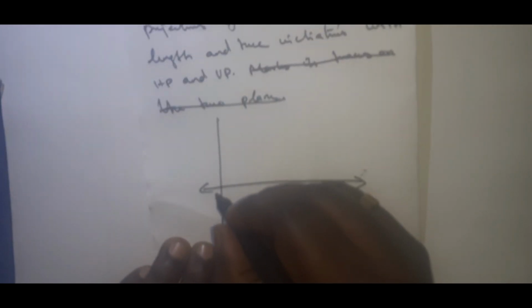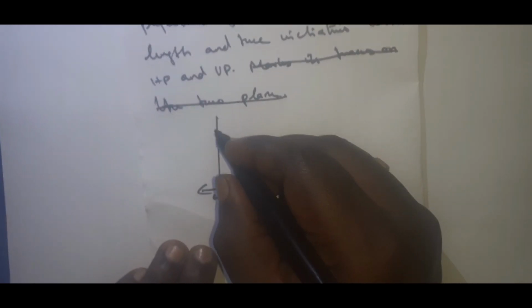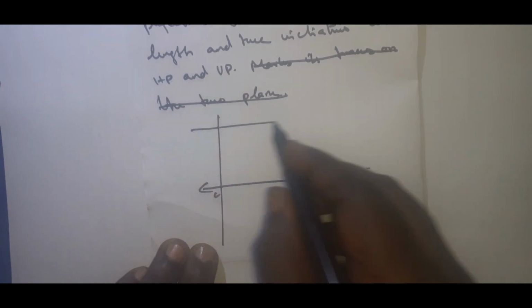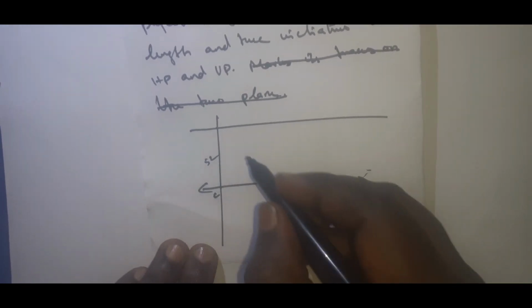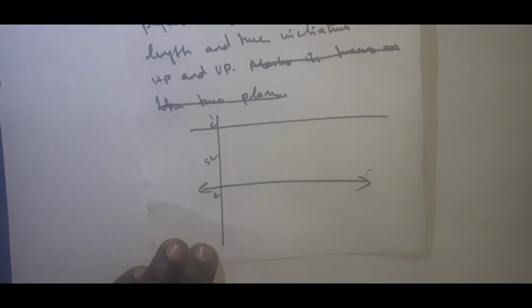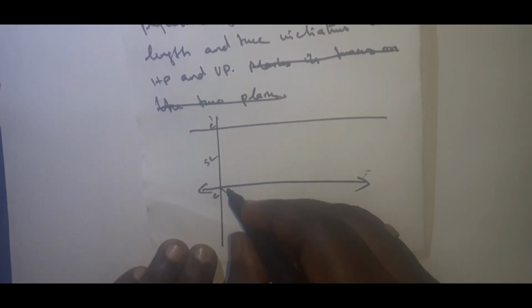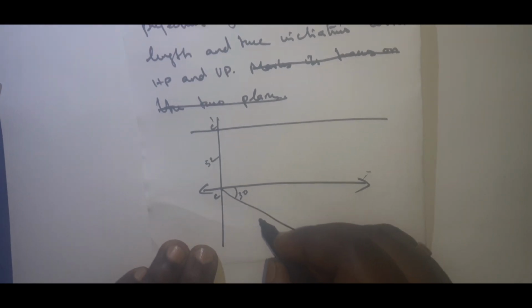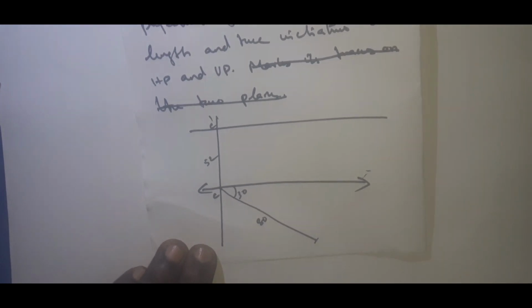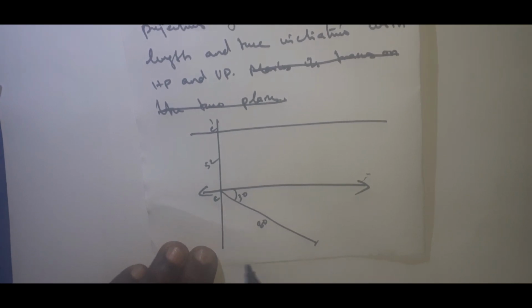So here this is in VP, C. And 52 mm above HP. So here you can measure, this is 52 mm above HP. This is 52 and this value is 0. Here this is C dash. Now you can make a 30 degree inclination line with a length of 80 mm. So here you can count the data 1, 2, 3, 4. 4 data we have plotted.